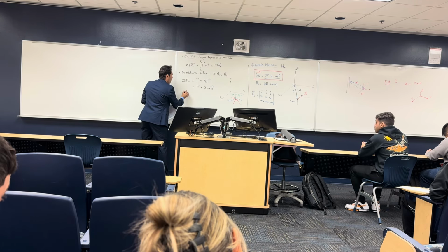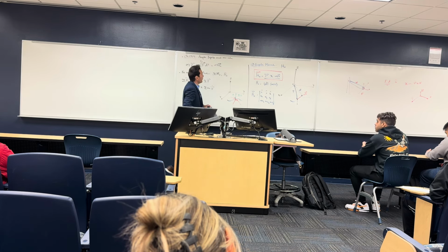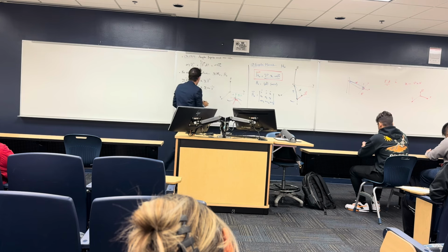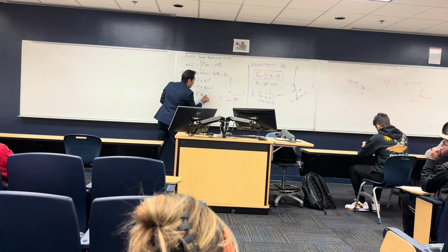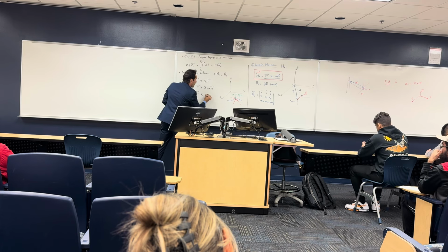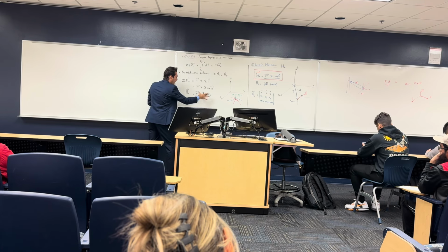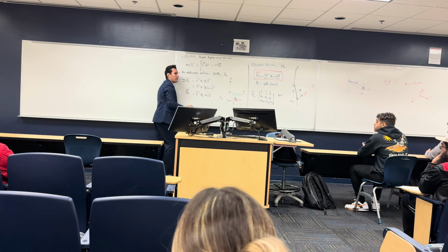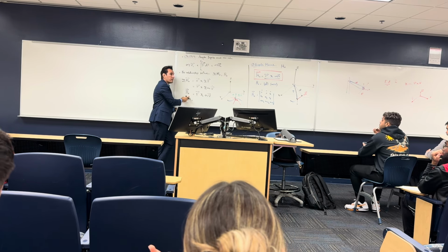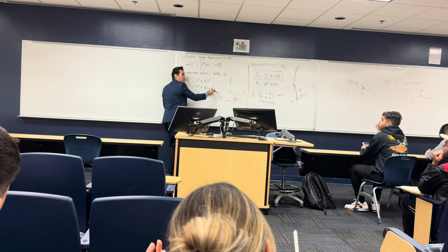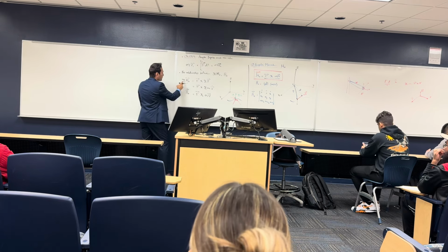So how about HO? HO vector, we just wrote it up there. Here, okay? It's the R vector multiplied by cross product mv vector, okay? There's a little bit of similarity here. This is kind of similar to this. What is the only difference that we have here between the moment and the angular momentum? Acceleration. Here this is v dot, acceleration, here is this velocity. So let's find out how do we get from here to here.